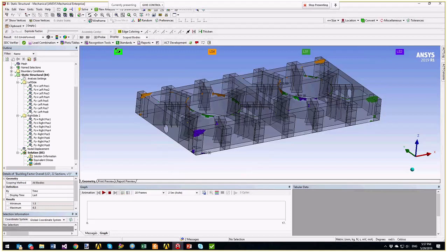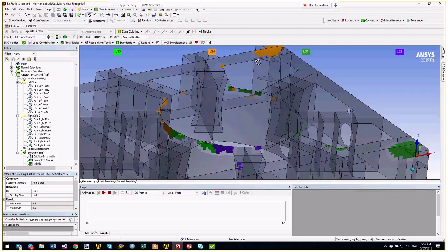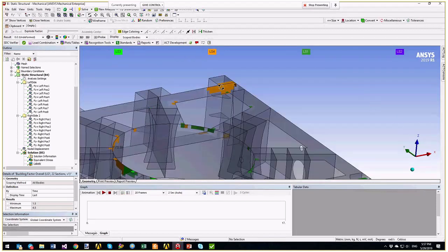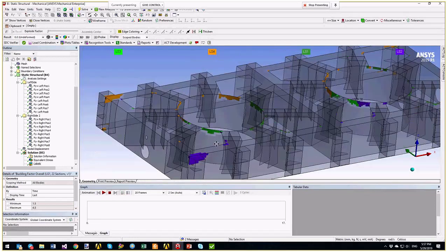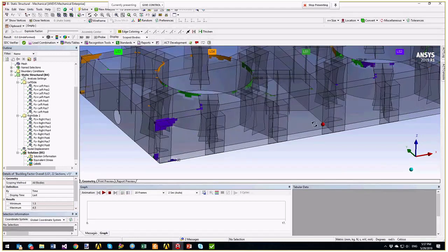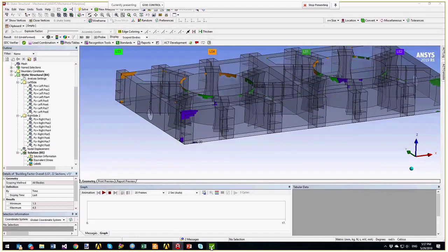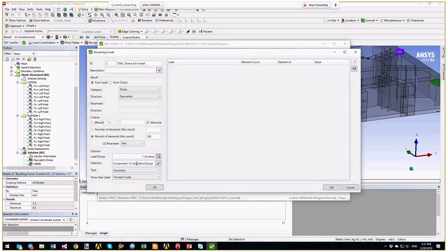As you can see, all loads are shown with labels and with different colors. If I want to see the elements with orange color, they correspond to load set 4, and it also shows me four labels with the highest values close to the elements of that load. I can do that with the criteria, or I can make the same picture for the full model if it's interesting for me. So I did that to show me the full model.